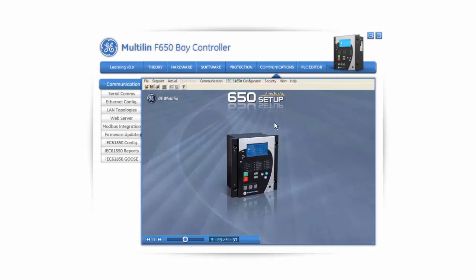Upgrade operating system. The boot code upgrade is performed using EnerVista 650 setup software. There must be no active communication between the program and the relay, and no configuration file can be opened.